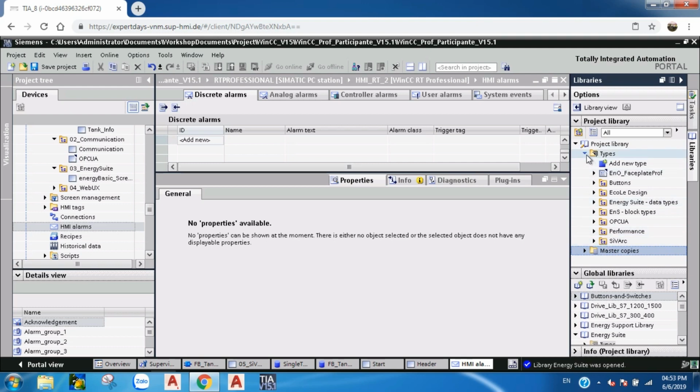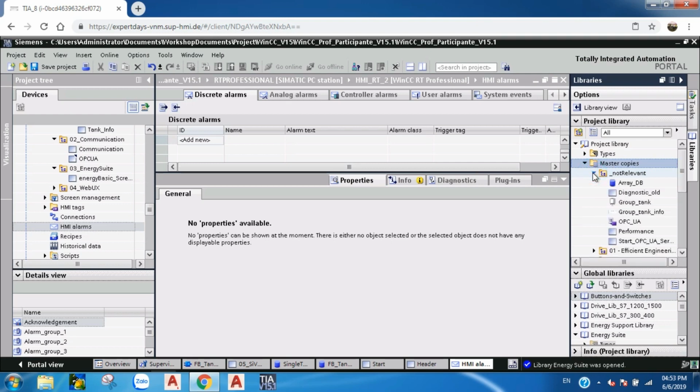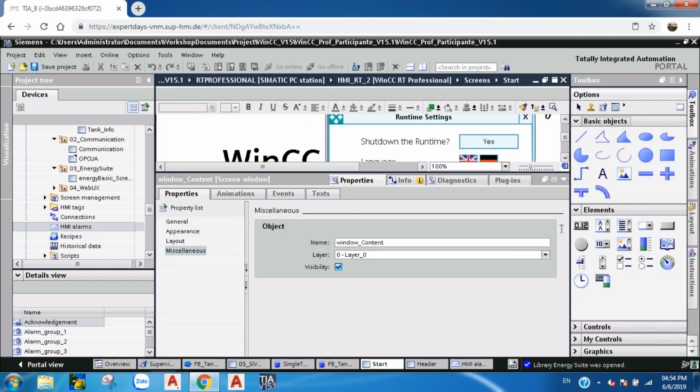And there I start over and say my first alarm rule. Now again, I want to have 3 alarms. Oh no, I didn't start the recording. I want to generate 3 alarms for each single tank. So again, I choose my single tank here. And master copy of alarm is the generated alarm in the master copies, on an analog alarm on line 1. I save, and I generate.